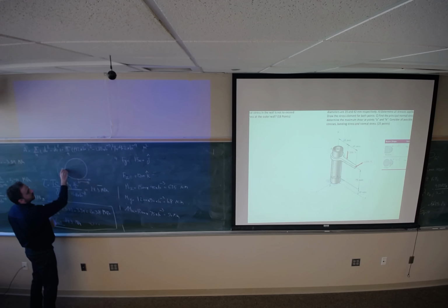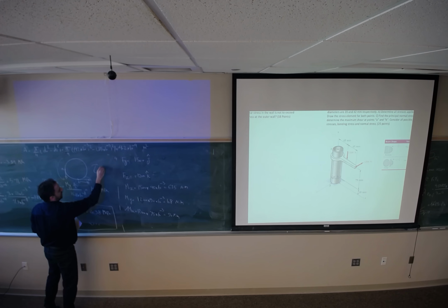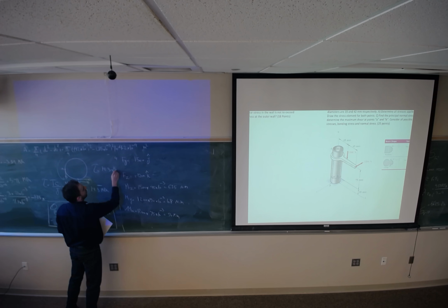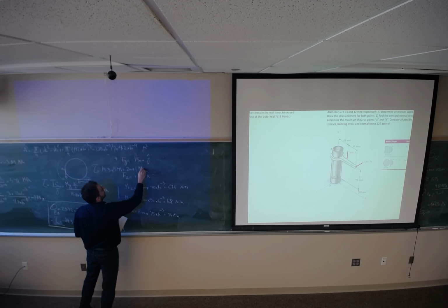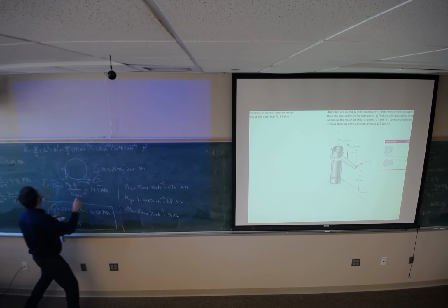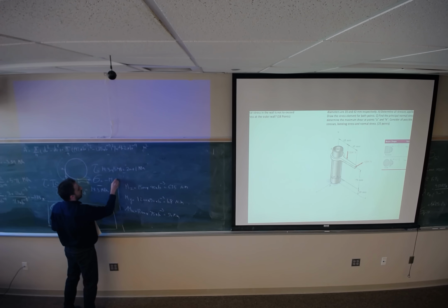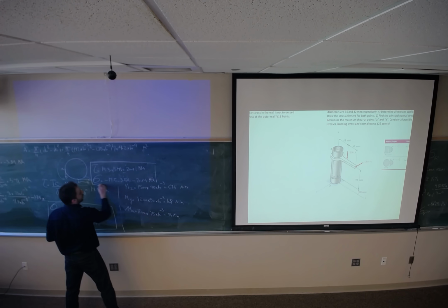This is gonna be 0. For this, you should add them up. So shear stress is gonna be 14.3 plus 5.71, which is 20.01 megapascal. And normal stress, -3 here, -17 here. This is for point B.